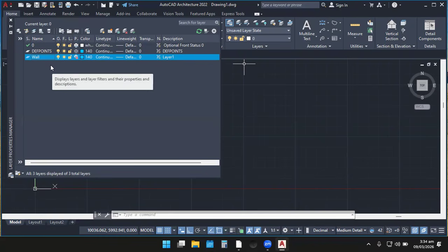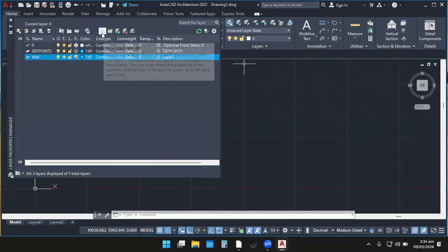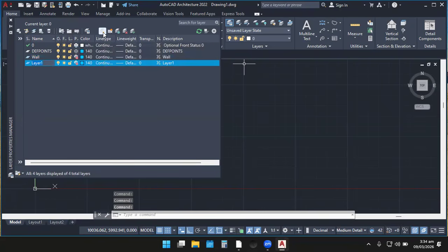Let's create a different layer for window. So I'm still going to come to new. See, this is new layer. Then I left click, then I backspace and I write window. Good. I'm done creating the layer for the window. Also, take note of these things that are highlighted over here, make sure you don't touch them. Let it be that way. If you're not careful with some of these things, you will face a lot of challenges. So let it be that way.